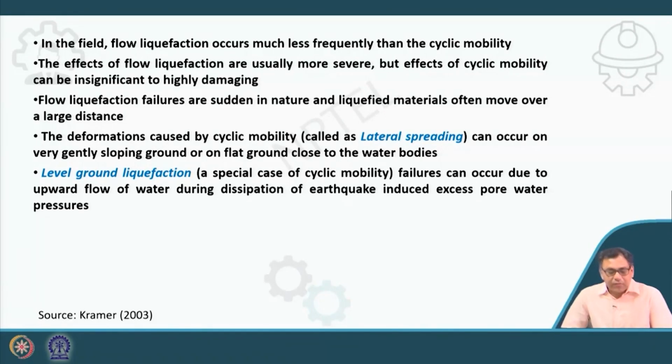The flow liquefaction failures are sudden in nature, and liquefied materials often move over a large distance, because when the shear strength is less than the static shear stress, flow liquefaction occurs. That is why this failure is sudden. But in the case of cyclic mobility, the failure is not sudden.